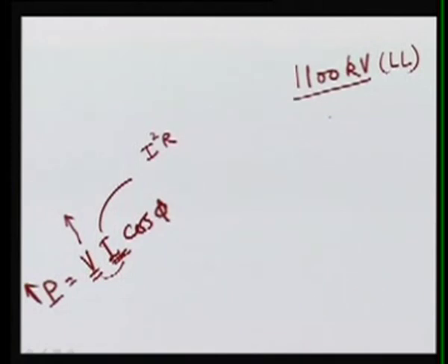However, in India we have this 800 kV system, again that is operating at the 400 kV system, but we have the line which is designed on this insulation level. Whenever you want to lift the voltage, increase that, you have to change the substation and apparatus, and then we can operate at 800 kV. And again we will see, when I will be discussing the transmission line, the surge impedance loading of this transmission line is very, very high, almost 4 times that of your 400 kV transmission line.